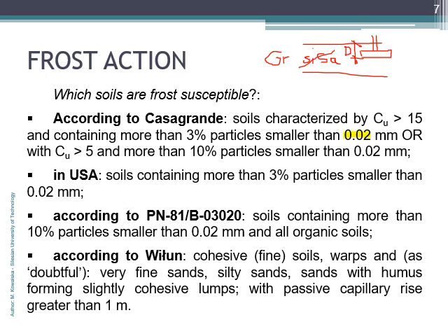It can be shallower, okay? So it is important to know what the frost susceptible soil is and what the depth of the penetration is, of course. And then you can use this information when designing the depth of the foundation. Okay, thank you.